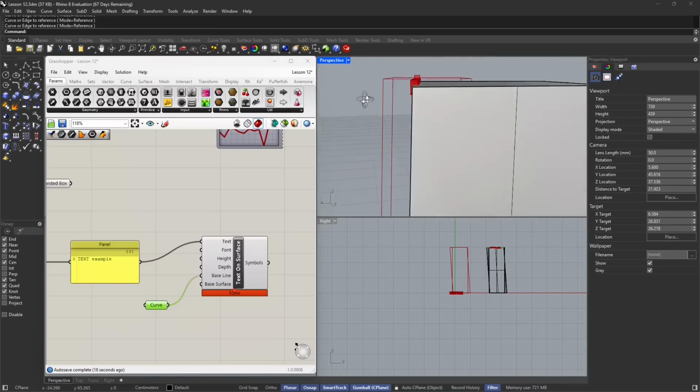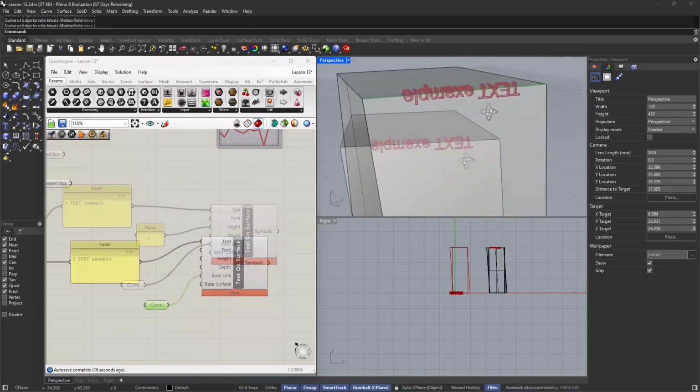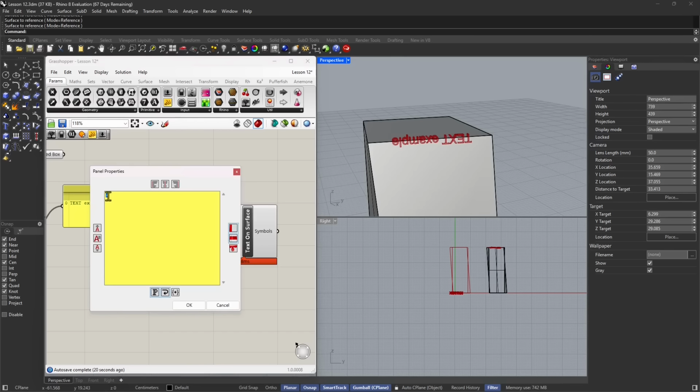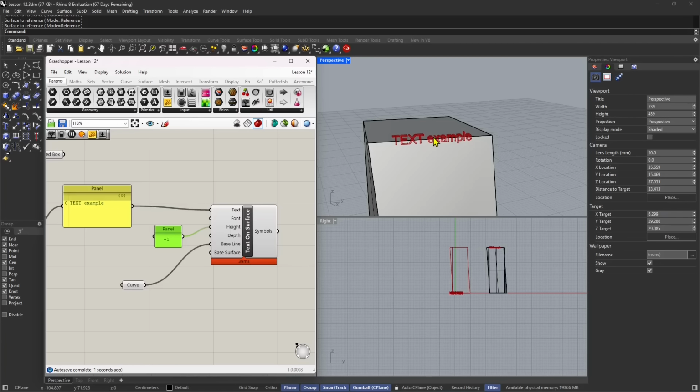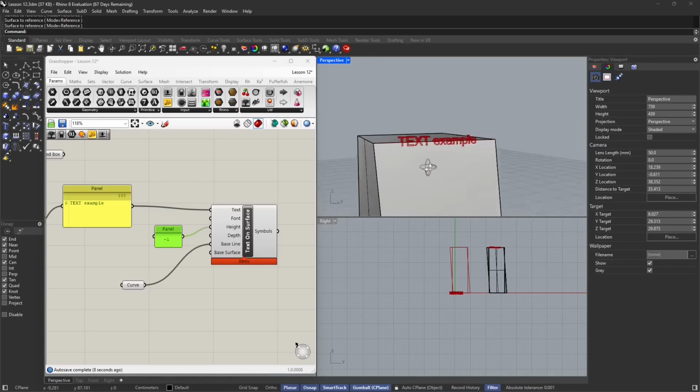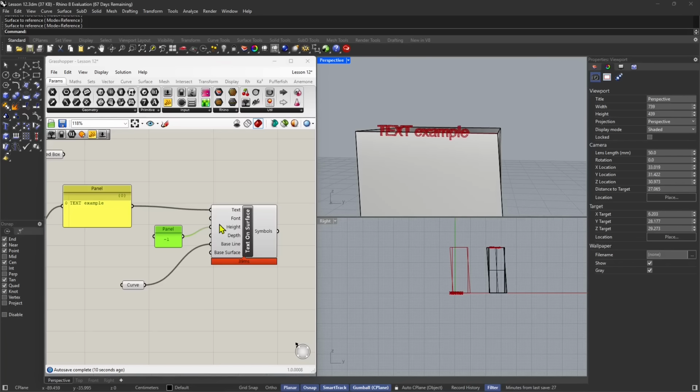You can see the text now is appearing exactly with the middle axis on that edge, but it's upside down. So I'm going to use a -1 parameter into the height to invert, in a way, the direction of that. But you know, there are also other ways. I'm just showing you some tips and various ways we can do things.